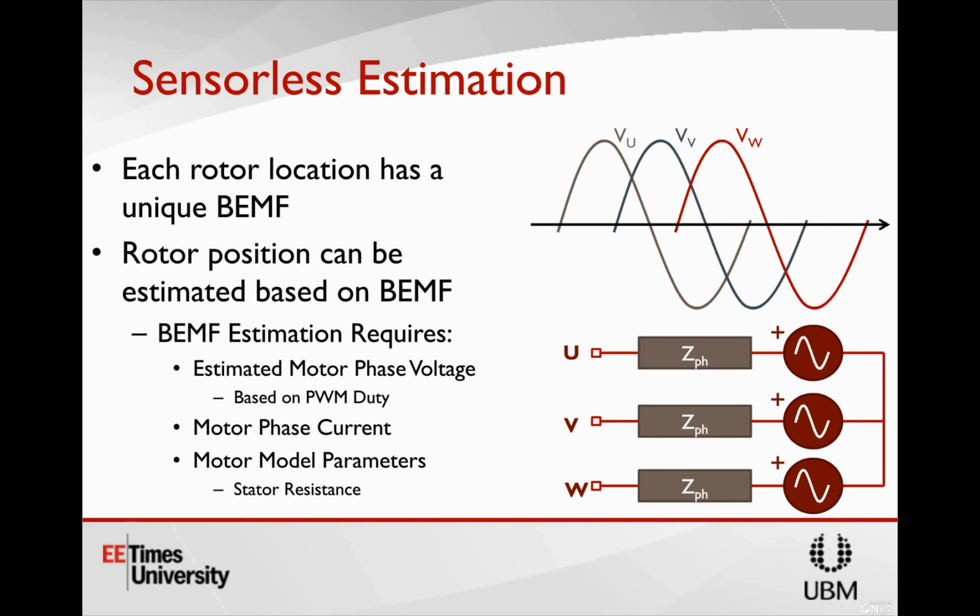Even if you're not running the PWMs, you still know the angle because you're always measuring it. In sensorless control, that startup period will be, like I described, on anything below about 10% rated speed or so. That's really the difference: in sensorless there is startup, and in sensored there isn't.